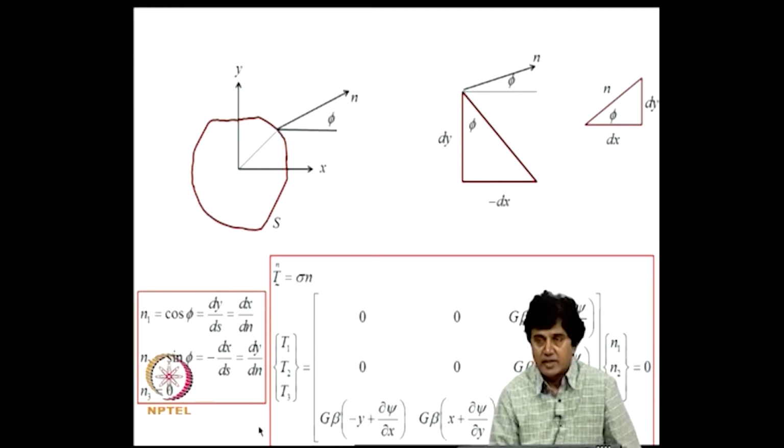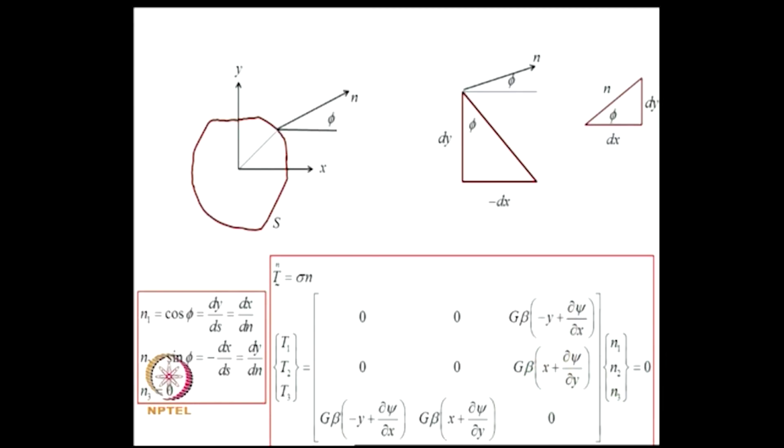Now, how about the boundary conditions? So, boundary conditions on the lateral surfaces, again we consider the surface traction is given by sigma n, and we consider the geometry, we consider a point on the surface as shown here, and n is a unit outward normal. So, this will not lie on this plane as it was happening for a circular rod, because this outward normal can be different.